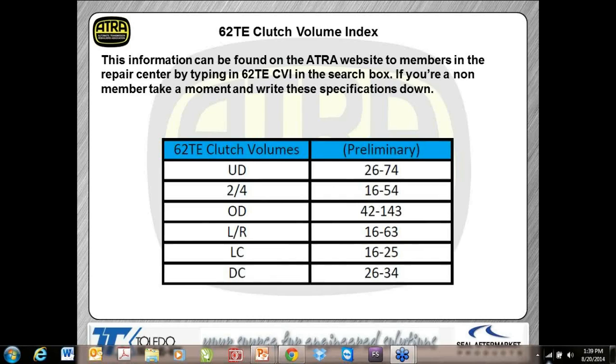Now, again, getting back to these direct clutch housings, if yours comes in and you have these codes, P0792, P0735, or you have issues with no line rise and it's got a real severe slip on the 1-2 shift, more than likely you'll take this apart and you'll find the snap ring is dislodged and the clutch pack has come up high enough where it's probably cut the seal. Again, if this comes into your shop like this, some guys have attempted putting in a heavier snap ring to try to keep it from coming loose, and sometimes it works and sometimes it doesn't. The bottom line here is if it comes in this way, you're going to want to just change the drum. I don't know of any updated part numbers at this time for a new drum.